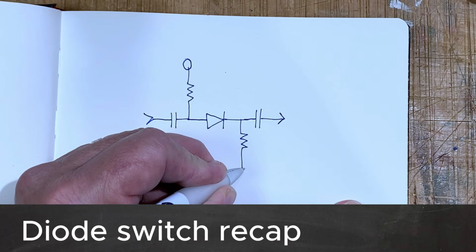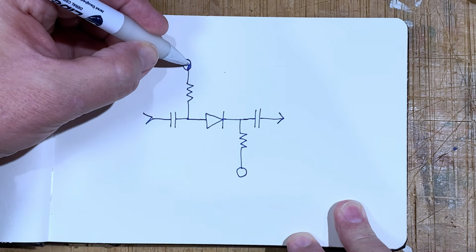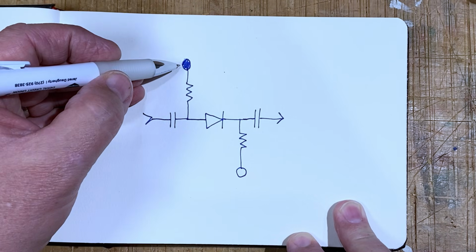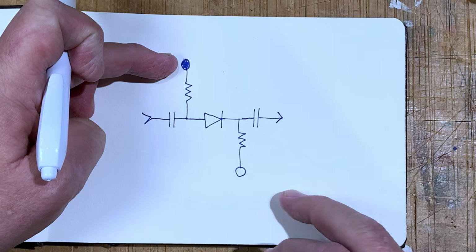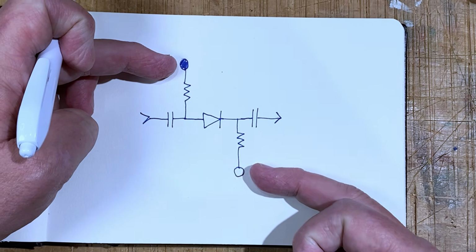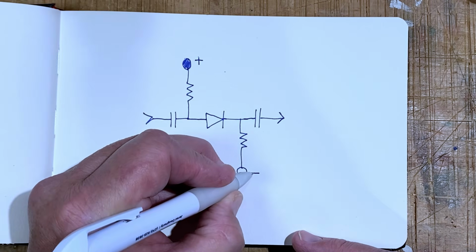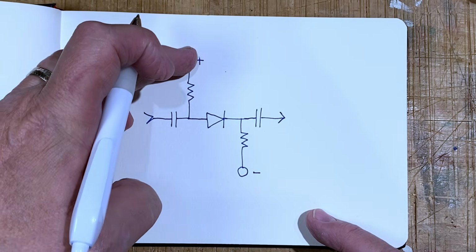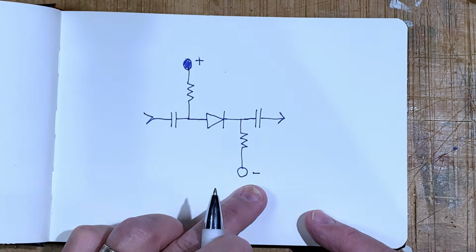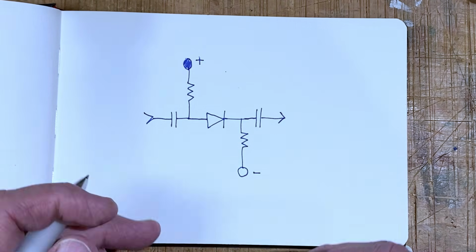To improve things slightly, I started playing around with applying 2 different voltages. So I had 1 voltage on one side and the negative, or the opposite of the voltage, on the opposing side. This was positive, I would make this one negative. So this diode would be open and the audio signal could pass through just as normal.